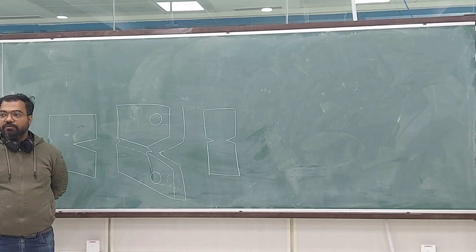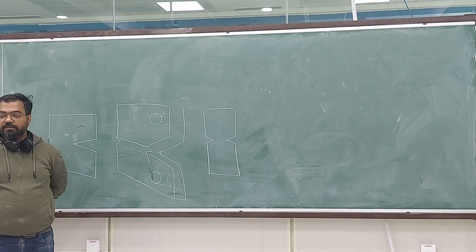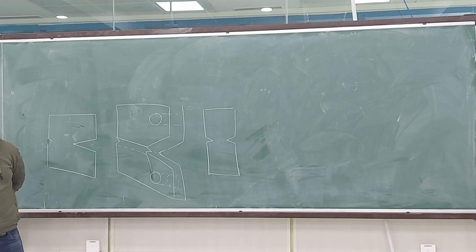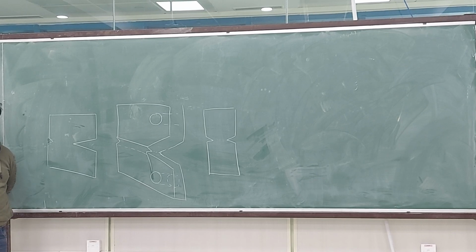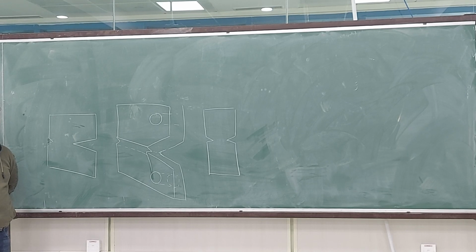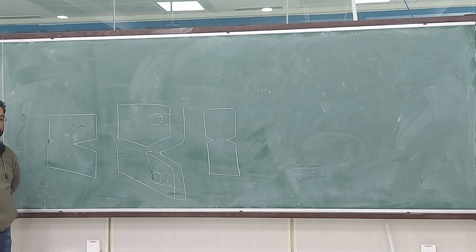This is called side grooves because these are grooves on the sides. Okay, so why do we do it? Tell me. So that the crack will remain on the same groove plane only. It will not deviate. So how do you ensure that by making this?